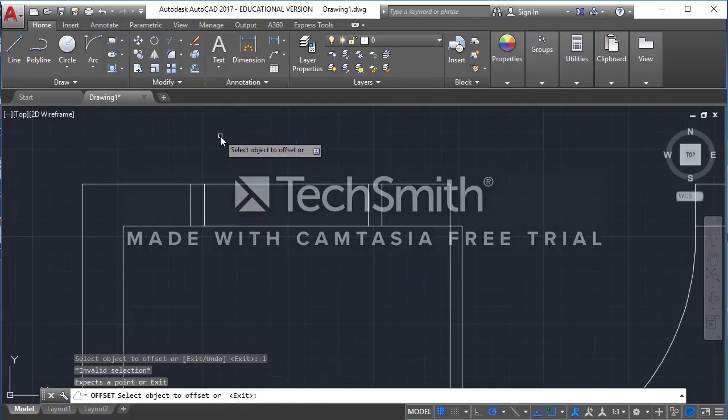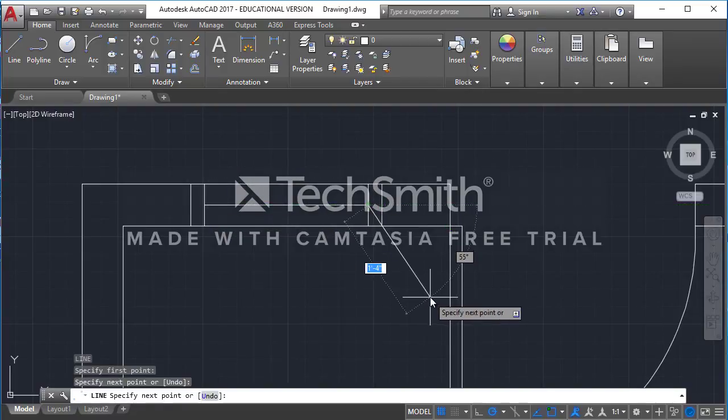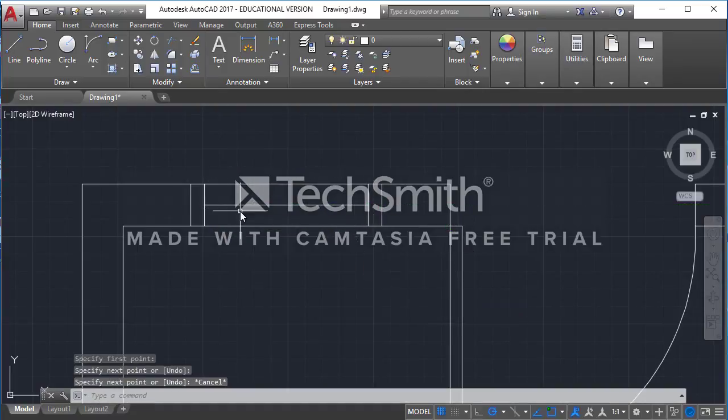All right, then I'm going to draw another line, escape, then hit L for line, and I'm going to draw that in the middle of my window frame. So that line represents the window pane. If you want to take it a step further, I could offset this line.